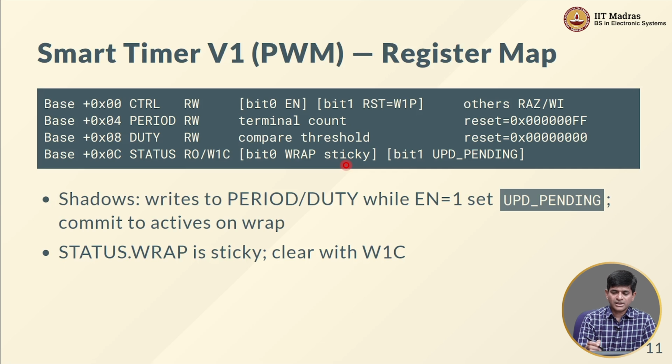It also has one more bit which indicates that there is an update pending. We will get to that in a moment. What exactly does update pending mean? Well, in short, what it means is, I do not want to change the value of period and duty cycle while in the middle of counting.